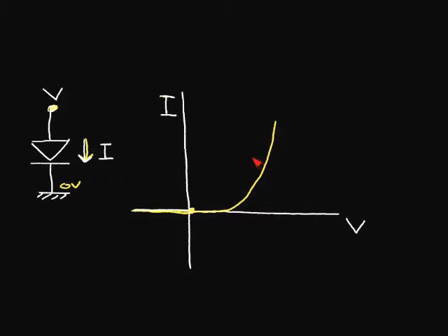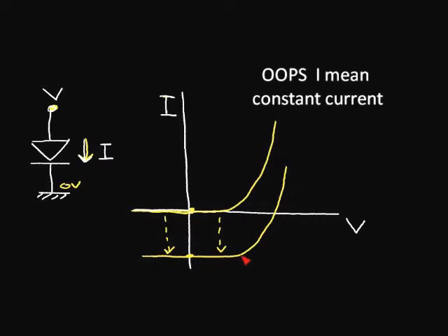Now what happens if we shine light on the silicon diode? So let's look at what happens if we add some light. Now this produces a different curve. The light causes this curve to be shifted down like this. And so at this point we have current flow. We have more or less a constant voltage, and the current drops off to 0 current at this point.